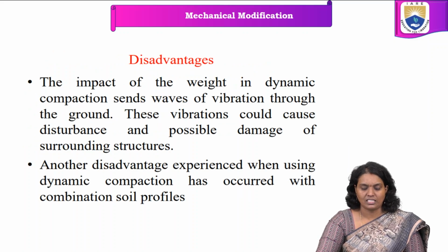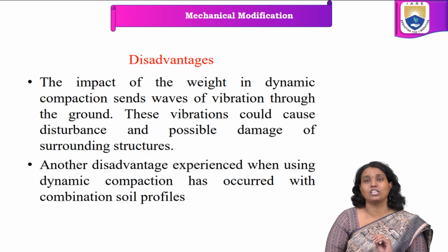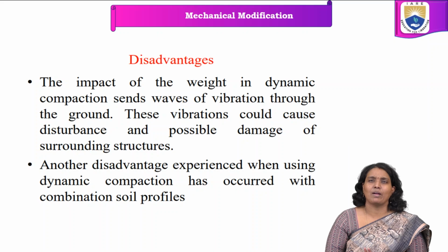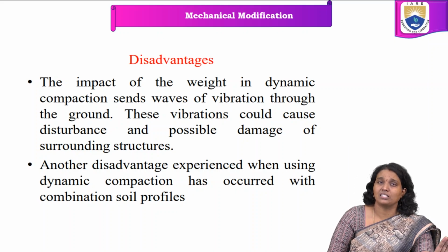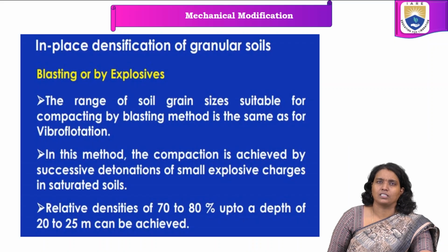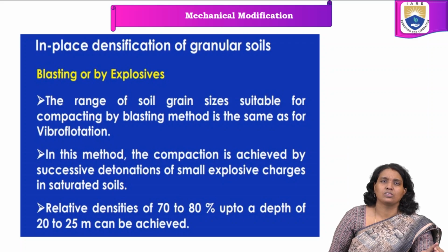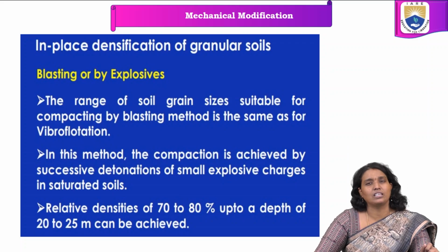Some disadvantages also exist. In dynamic compaction, the combination of soil profiles and the vibration could cause disturbance and possible damage to the surrounding structures, which is the major disadvantage of deep dynamic compaction. Then there is in-place densification of granular soils by blasting with explosives.